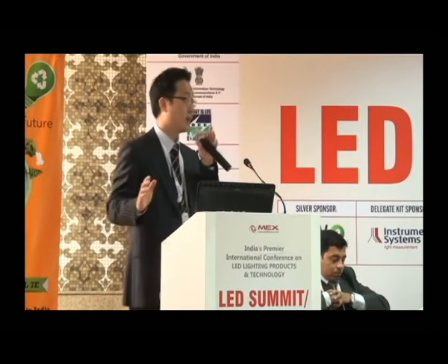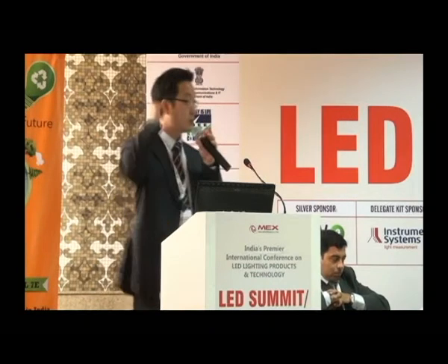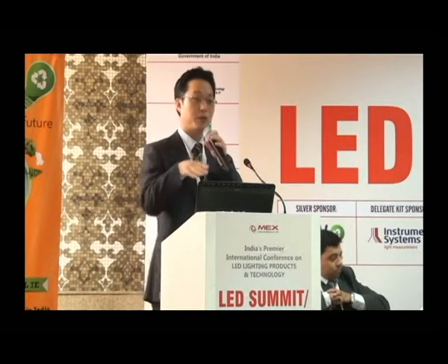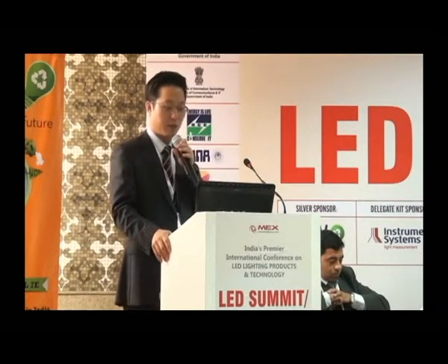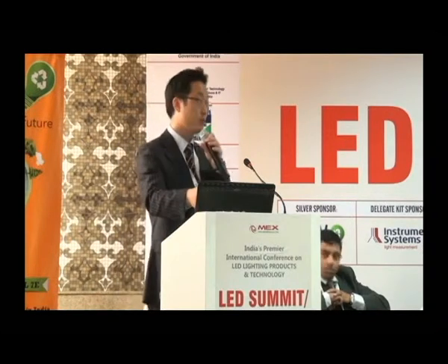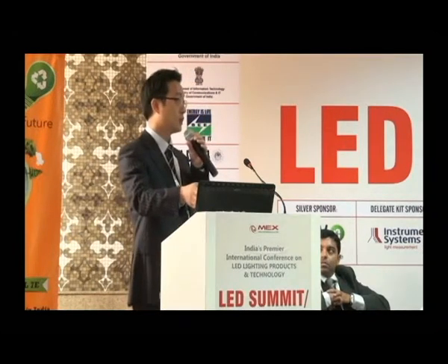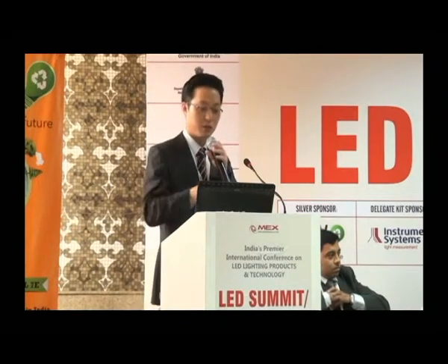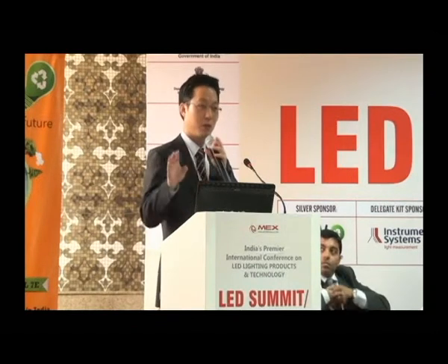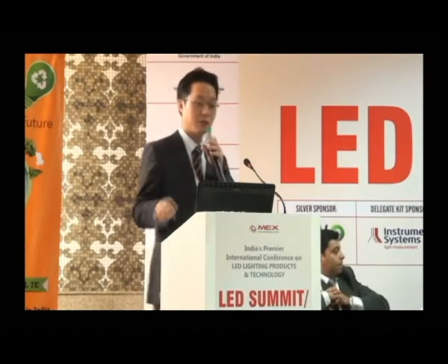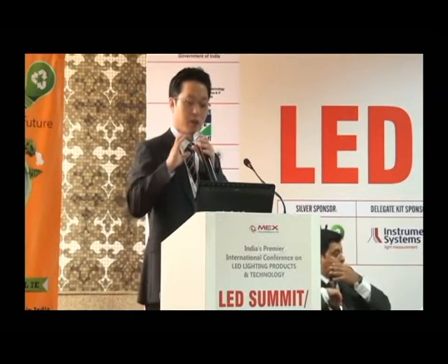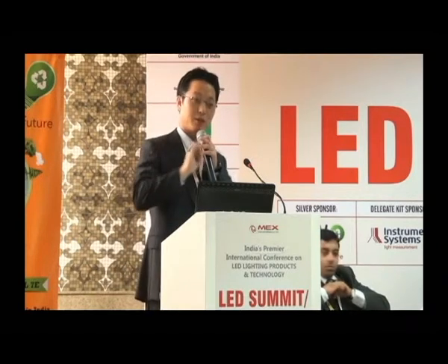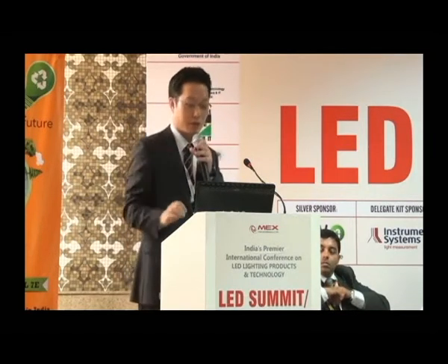That is the reason why LED lighting customers would like to make uniform phosphor-dispersed LED chips in their production line. So this product is designed for such a request. Normally 1 day is needed, but for over 2 days there is no phosphor sedimentation, so you can make uniform LED lighting from the bottom of the cartridge to the top of the cartridge.